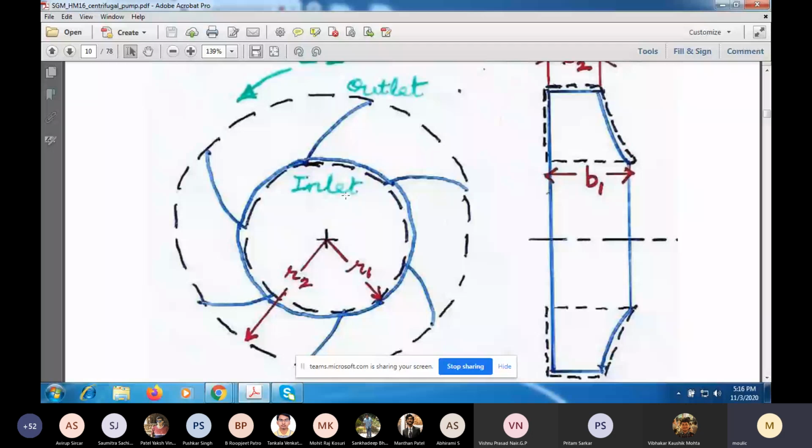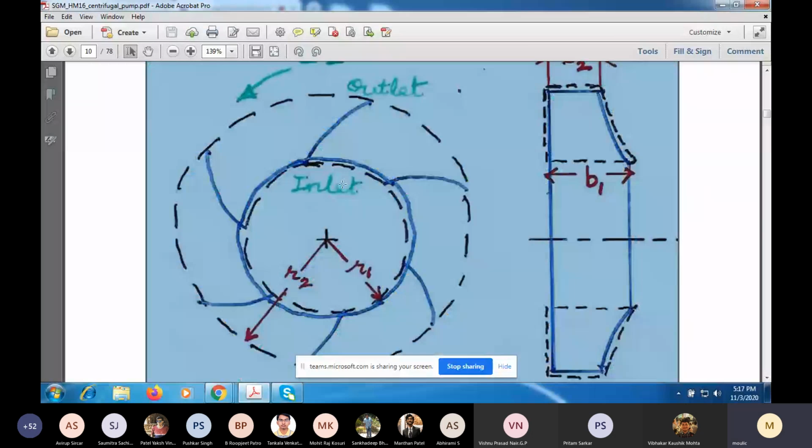So that is minus er. So V dot n is negative. So that means fluid will enter the control volume through this. So I marked this as inlet. And this is the outlet.